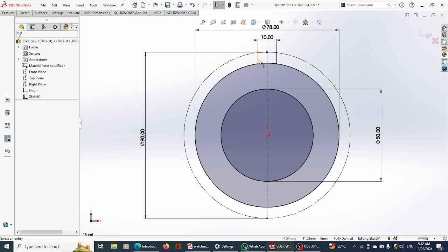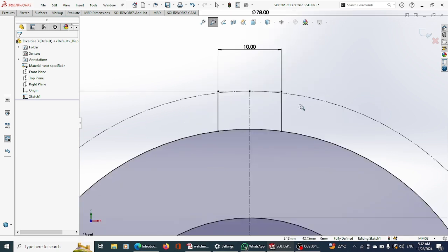So I'll hold Control. Now when you are selecting a line, if you see this point highlight, please shift the cursor downward. Don't allow it to be close to this point. If not, it's going to select both the point and the line. So go downward. See, it's already selecting another point. So be careful. If it's happening like that, you can easily zoom, as I said before, so you don't make mistakes. Good. You can drop the zoom by hitting the escape key.